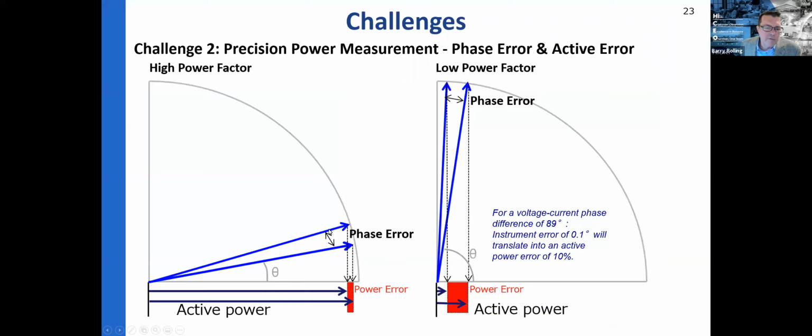Let's introduce a small phase error, several degrees, and that same shadow cast almost the same active power shadow onto the x-axis, and that is active power, and that is the relationship between S or S prime and the x-axis. That's the active power. The shadow is the active power. So that's a happy day, easy to measure, and that's where a lot of our power exists going into a motor. But there is significant power up at 30 kilohertz or 50 or 100.